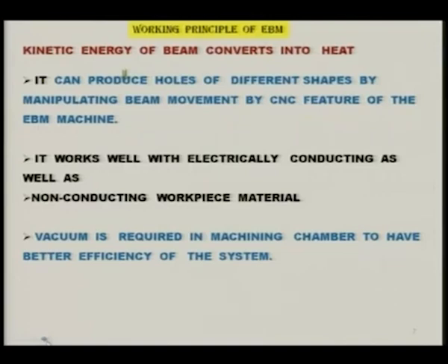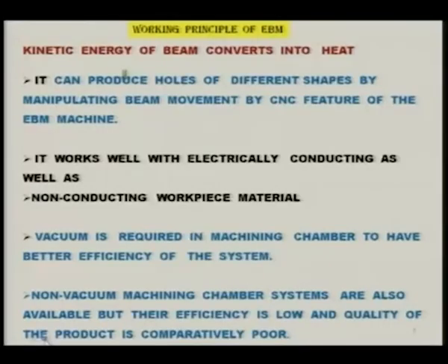Now vacuum is required in the machining chamber to have better efficiency of the system. Most of the EBM systems are vacuum operated, means they are operated under vacuum. However, certain systems have been built which can operate with a non-vacuum machining chamber. Such systems are also available, but their efficiency is low and quality of the product is comparatively poor.